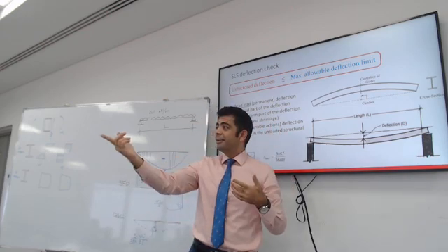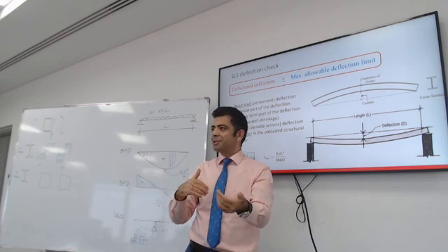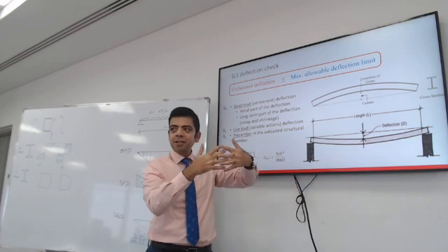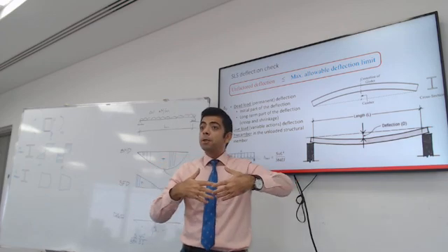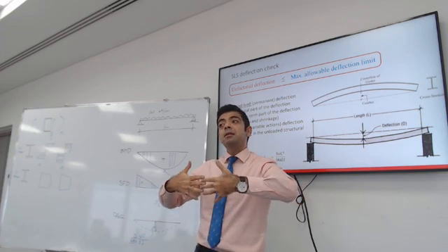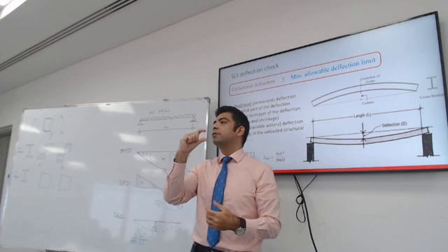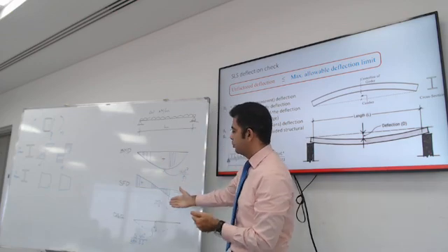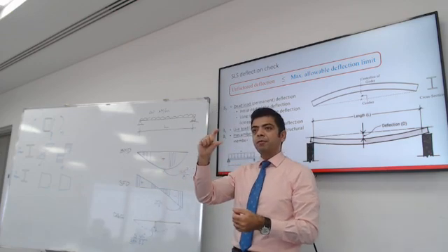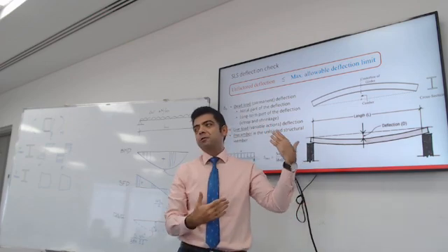After putting the load, it will be balanced. To balance the dead load deflection, right? The dead load deflection is downward. So you can balance the dead load deflection by manufacturing the beam cambered upward by the amount of the dead load deflection. So it's important to be able to calculate the dead load deflection, and you may want to specify a camber on this structural element.